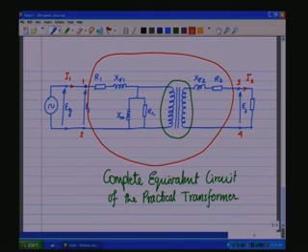Now, I1 flows through the primary leads into the transformer, it gets split here as I0 and it goes through here as IP, ideal, I primary ideal, and on the secondary side you have the current I2 which is flowing through, and here you have IM, the magnetizing component, IC, the core loss component of the current.